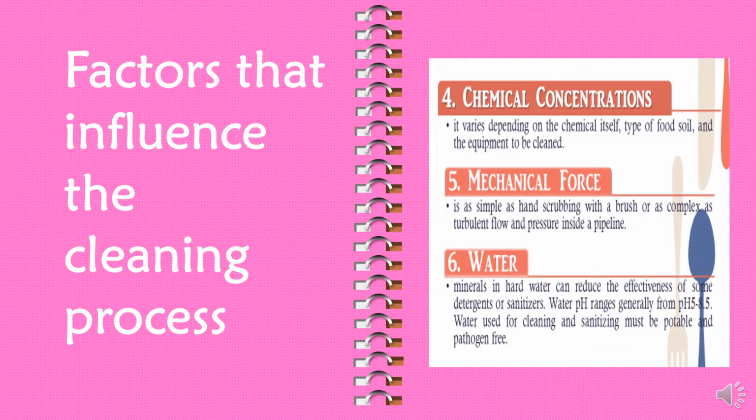Another factor that influences the cleaning process is the chemical concentration. It varies depending on the chemical itself, type of food soil, and the equipment to be cleaned. Concentration will normally be reduced as time and temperature are increased.